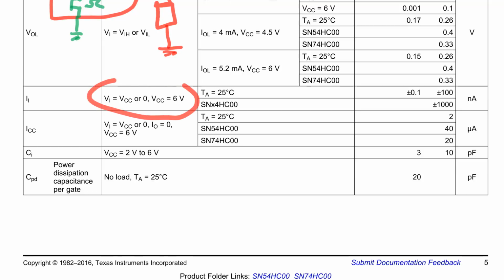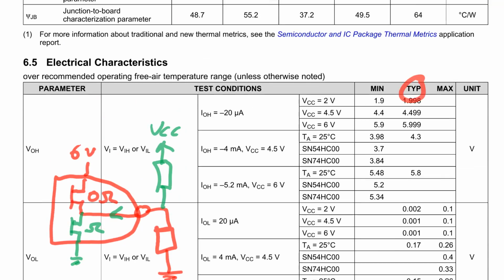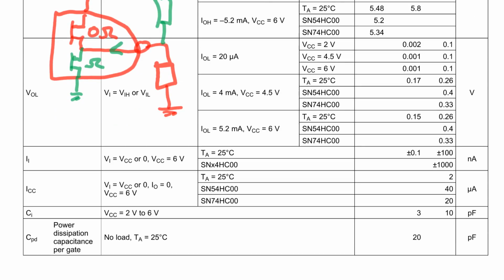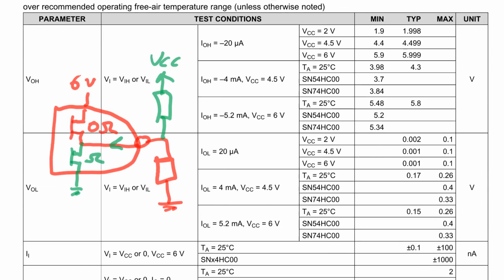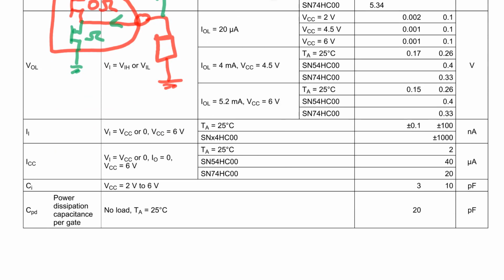They're basically saying just over the full operating voltage range there, once again at a typical ambient temperature. And once again, we have a typical value here. You'll see it's typical, and you can use that. But once again, if you were doing worst case design analysis, you'd go with the maximum, okay? And there's a hell of a difference.